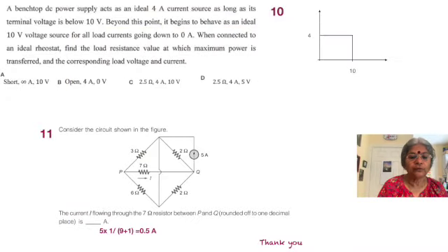Moving on to the 11th problem, we have a circuit shown with a 5 amp source pumping current through a network wherein the top node and the bottom node have been connected together, or shorted together, making two separate circuit elements parallel. For instance, the 2 ohm and 2 ohm are going to be in parallel across the 5 ampere source, and we also have 3 ohm and 6 ohm in parallel. Then thereafter they continue with the 7 ohm and return back to the source.